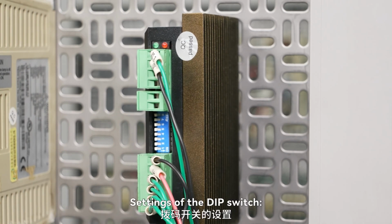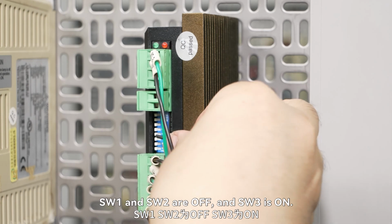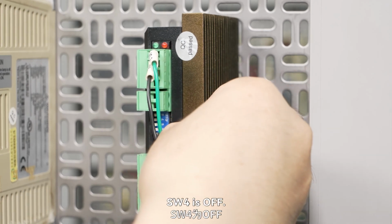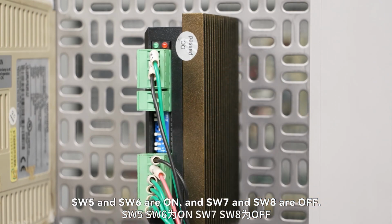Settings of the DIP switch. SW1 and SW2 are off, and SW3 is on. SW4 is off. SW5 and SW6 are on, and SW7 and SW8 are off.